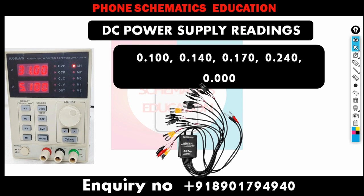The first one: when you set the DC power supply and connect to the motherboard on the battery connector, it boots up 40, 50, 100, 140, 170, 250. When you release the power button, after that it goes back to zero.